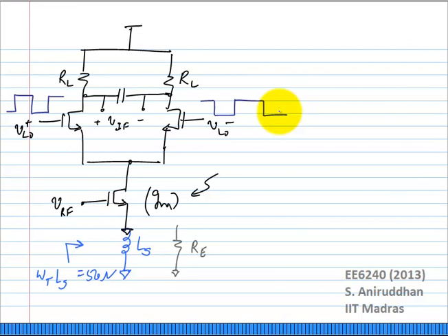What happens? At any time, either M2 or M3 is on. Correct? And since they switch instantaneously, they are going to be in saturation, with a well-defined bias current, which is the bias current through M1. So they have a particular VGS.